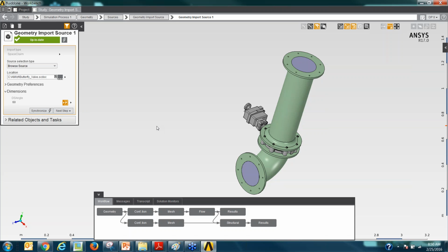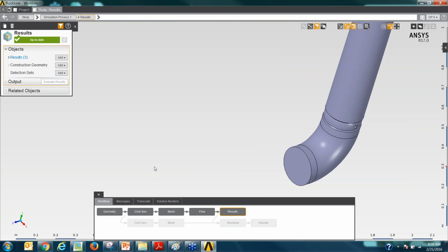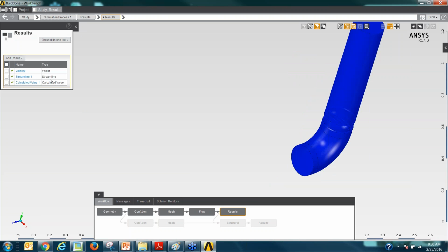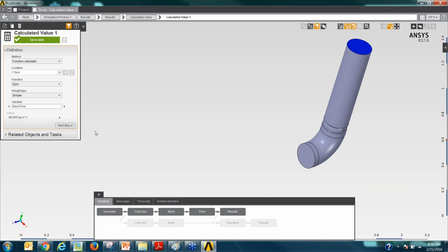That's an input. Now, what are the outputs I'm interested in? I can go to my results here, and there was this mass flow rate that I had calculated for the fluid flow. That's something I would like to keep. So all I'm doing is simply clicking on the parameterize icon right there. I'm adding outputs and inputs from my AIM analyses into my design point dashboard. That's really what I'm doing here. Now, the good thing is it's not limited only to flow, right?